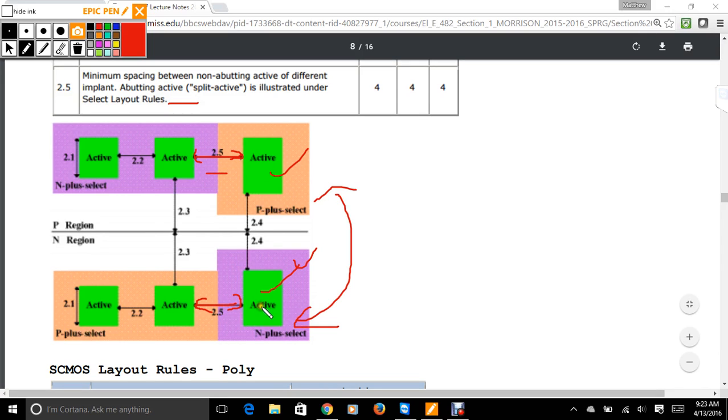To make it work between the active ranges. Does that make sense? The reason this is done: everything we've done up to this point, the pull up and pull down networks, their geometry has been the same. But sometimes you may have something like this, where, this is not a great drawing of it, but in order to get the geometry to work and be able to optimize power consumption, you actually can flip it around, and as a result, you need a specific space between them.